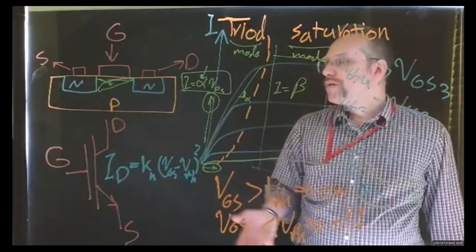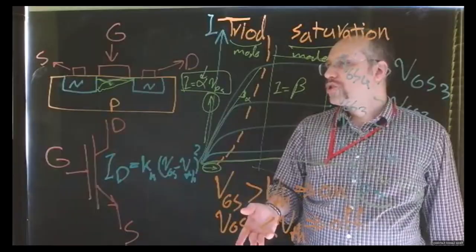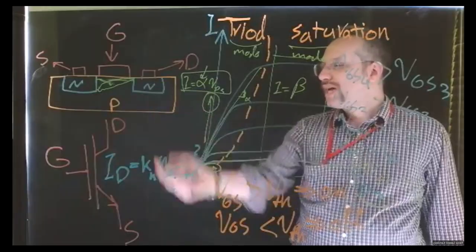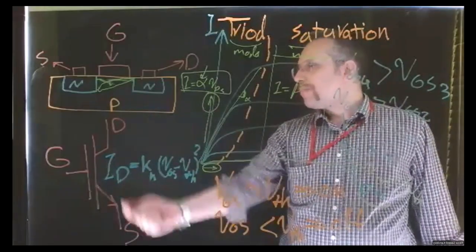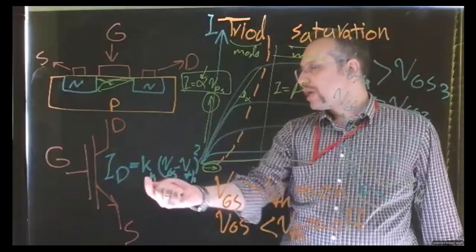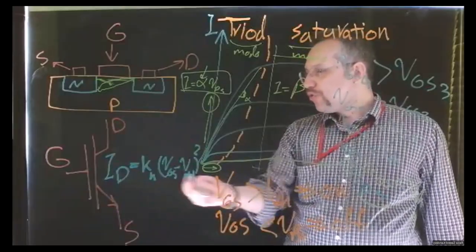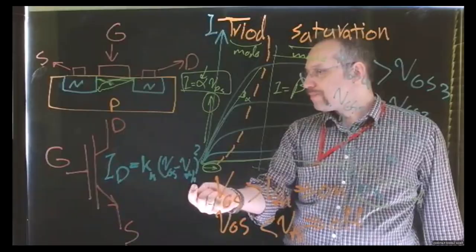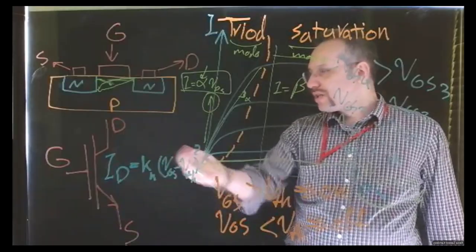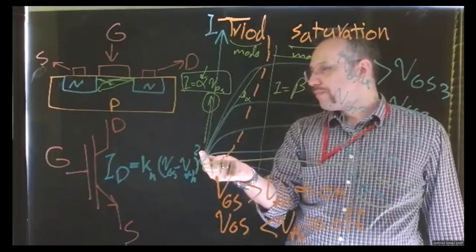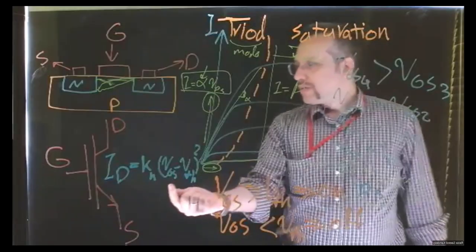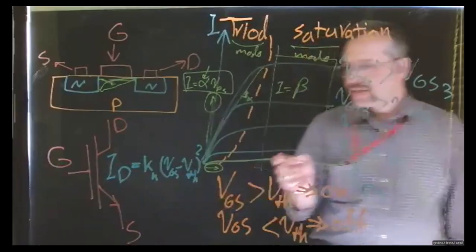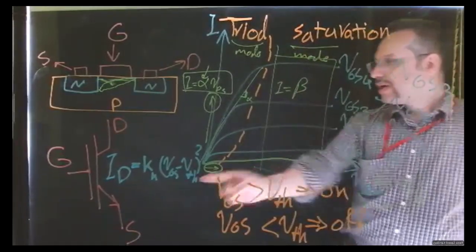If you do the small signal and large signal evaluation and analysis of the gate of the MOSFET, you can find that the current passing through the drain is equal to Kn times the difference between VGS and the threshold voltage, and all of that difference is squared. So if we increase the VGS, as you can see in the graph, we have more current.